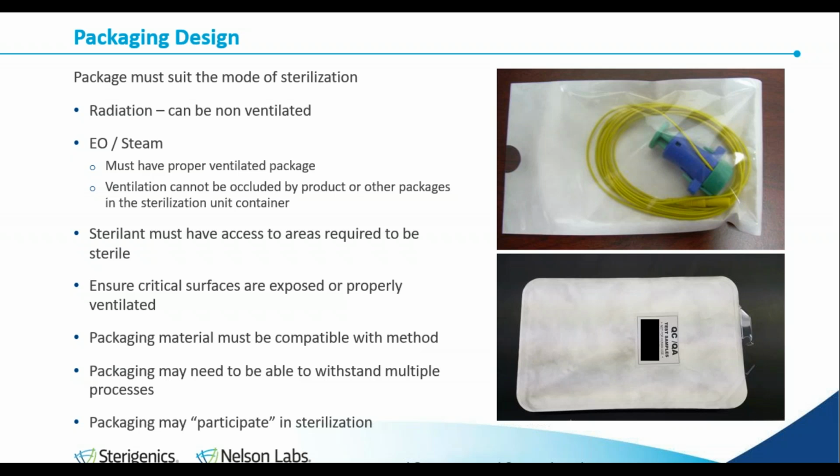And the thing was, they put those products into their shipper box and then stacked products one on top of another, and the polymer side of one package fit nicely completely over the ventilation patch of the next package, hence resulting in not only non-sterile product, but resulting in damage as well, because the lack of ventilation caused the packages themselves to blow their seals up when a deep vacuum was pulled.